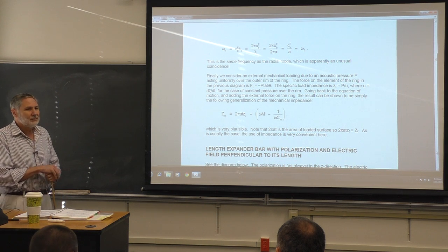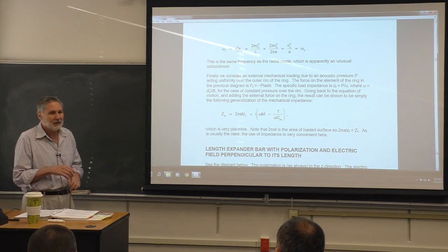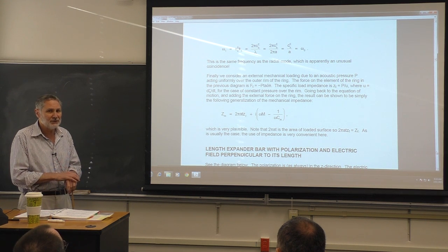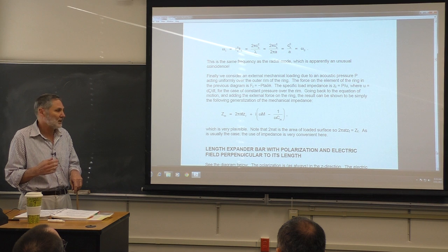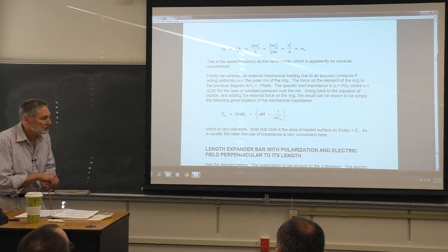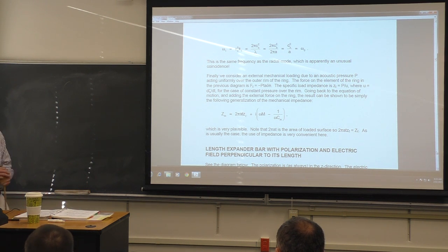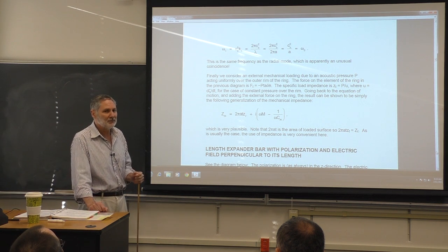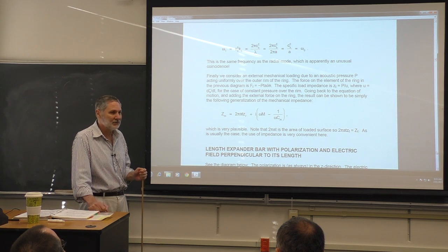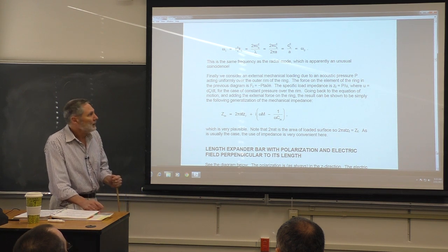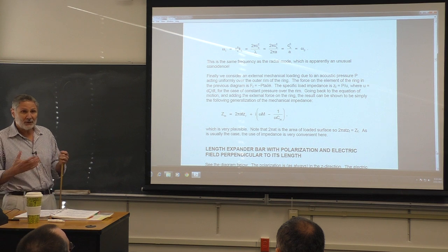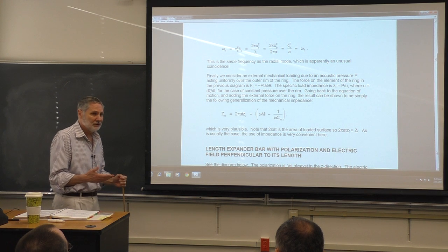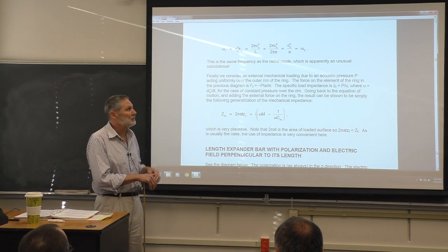Now, we assumed, if you look back, we have no load on this. To sonar people, what that means is you're operating in air. I keep telling you this, and I'm going to keep telling you it, because it's an incredibly useful thing. You have to test transducers. You can't trust manufacturers' specifications. You have to scope them out. You got to check them. And one way is to get those parameters that you need to calculate the sensitivity, for example, right?